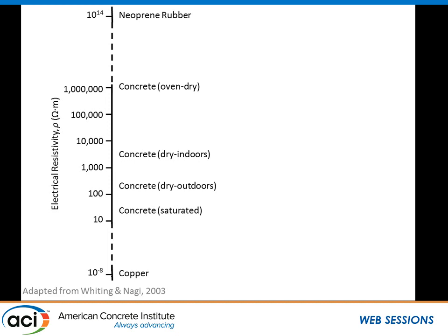And I think this is a very important point to mention here. That range there is basically occupied by concrete in various different moisture conditions. It's the same concrete. So you can see there, saturated concrete is somewhere around 50 ohm meters. That would be a typical result for a straight Portland cement concrete without any blending materials in there like fly ash, slag, and silica fume. But just by drying that sample, reducing its moisture content, we can change the result we get. So you really have to remember that resistivity is a function of the moisture content, and if you're not measuring saturated samples, you're really wasting your time because the result can be meaningless.